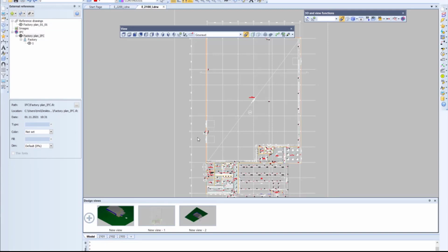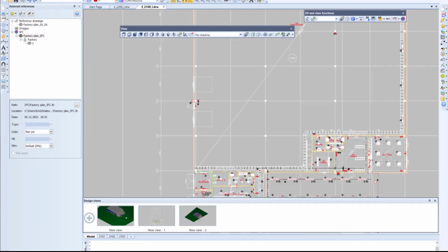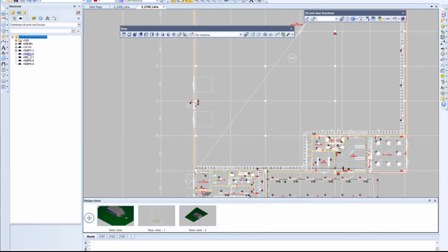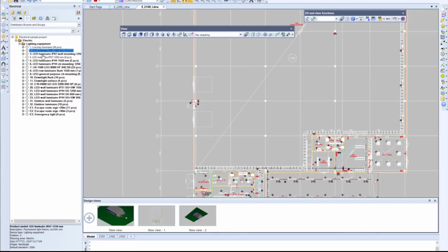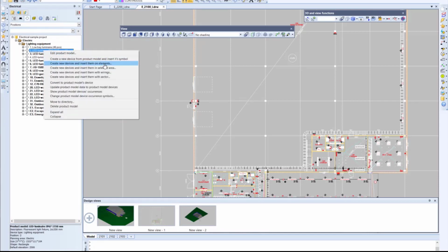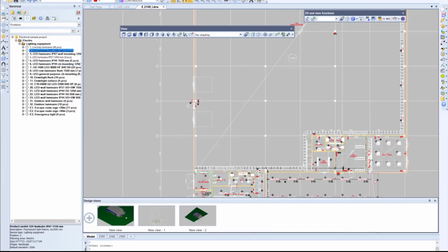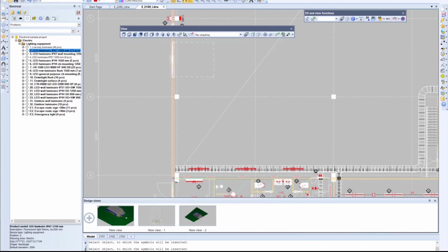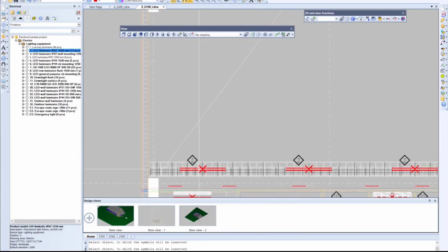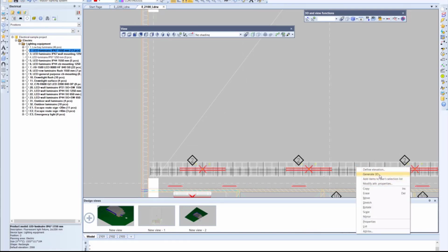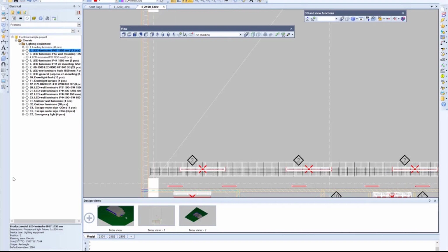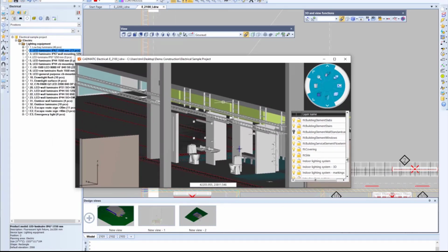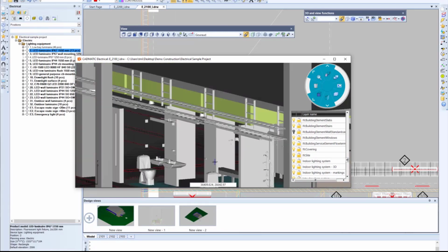Then we come back here. Then we are going to insert a couple of light fixtures to this raceway here. For example, these ones here. And I inserted them to here, like this. Then I can generate quickly these three. Like this. And now I can drag back the visualization window, and you can see that now there are these three light fixtures on the raceway.